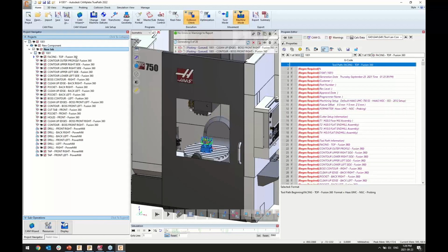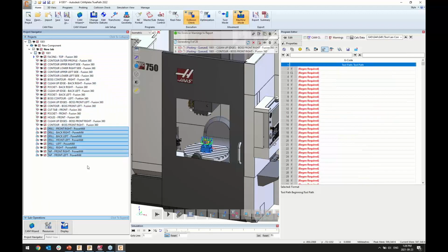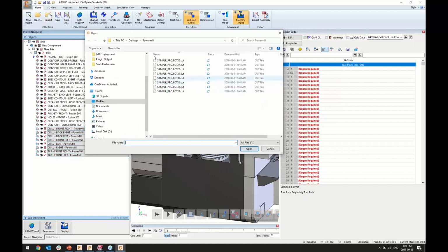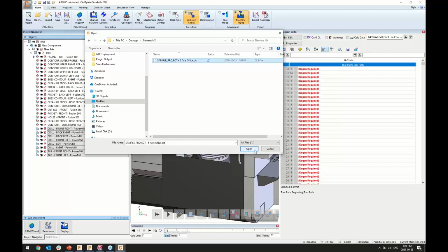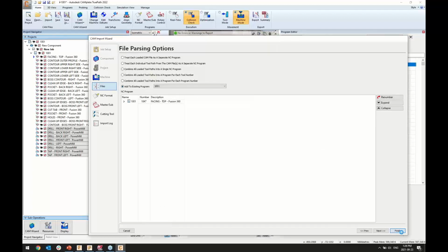So now the process becomes a little bit more interesting, where I have some Fusion 360 toolpath that I started from, I have some PowerMill toolpath that I started from, and now I'm going to add a little bit of 5-axis as well, and I can use, for example, some toolpath that was created from Siemens NX, and again, add that exactly at the end of my existing process.